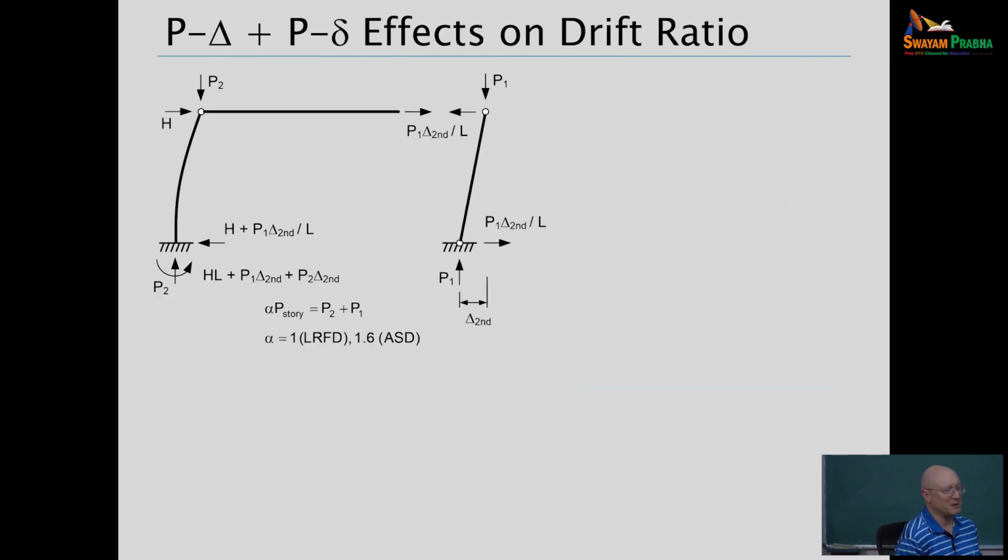Now let's suppose we've got some gravity load also on the lateral load resisting system. So the leaning column on the right here is just a surrogate for a whole bunch of gravity framing that's just columns that aren't providing any stability or any resistance to load themselves, but are carrying vertical load to the foundation. So I've got my one column here on the right representing that, and then the cantilever is representing whatever is providing my story sidesway stiffness.